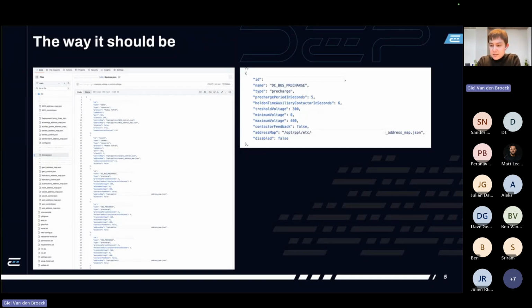So before we had this, when we had to implement a pre-charge sequence, we had to define a function block in the IDE of the PLC. We had to copy paste that function block. We had to link it to the digital I/O in there. And these pre-charge units actually come in 10s, 20, 30 units. So that's just one example where you have a lot of repetition in your code. And then something changes, and you have to deep dive into those function block diagrams that you developed.